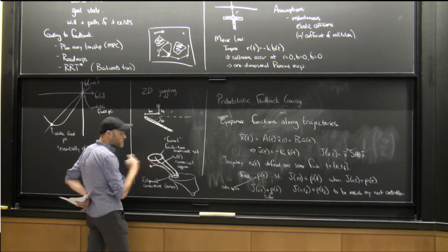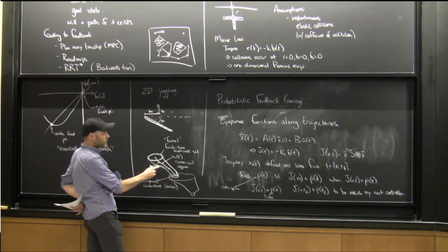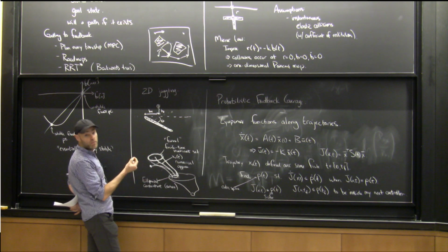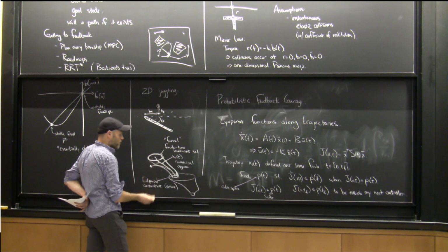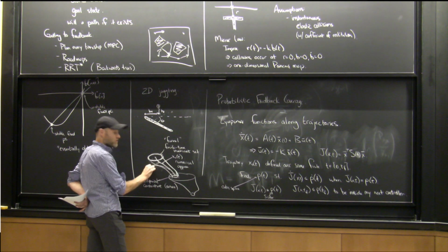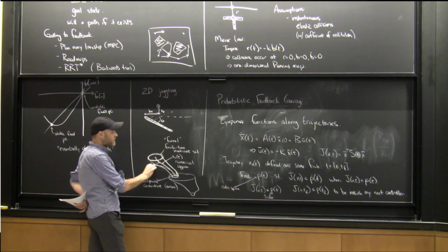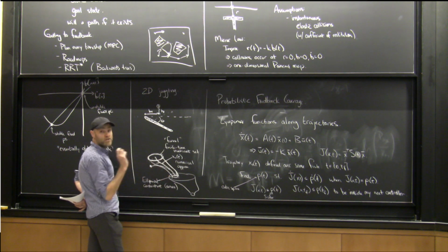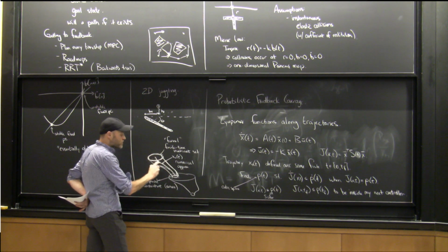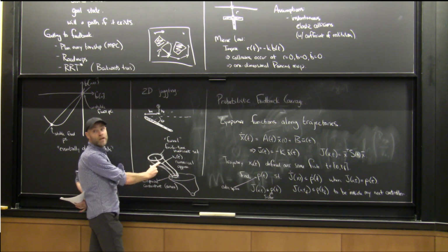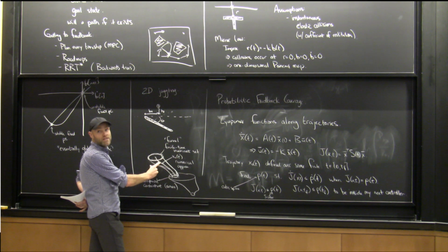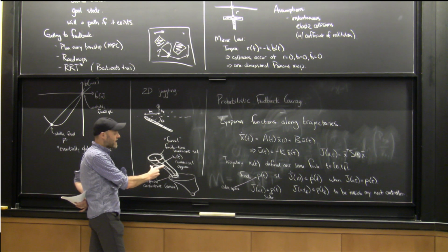Having decided that we're going to use trajectory optimization, there was a really important twist on this, which is that we formulated a trajectory optimization which says the initial condition is my sample point. The final value constraint is you're somewhere on the tree. My initial guess is a straight line to the closest sample, but as the optimization progresses, it's allowed to walk up and down the tree in order to connect.